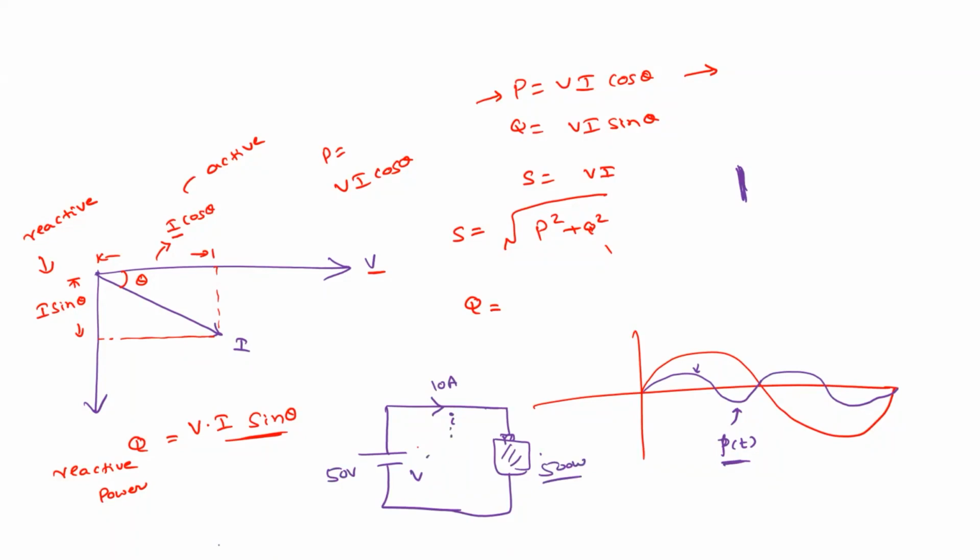So both V and I are positive, right? For example, if the current is flowing in the opposite direction, now tell me. Minus 500 watts. What is the meaning of this minus 500? It means power has been drawn from the load. Right. So here the energy stored in the battery is being delivered to the source. So this is the power flow in the opposite direction, that means from load to source. Agree? Yes, sir. The previous one was source to load.